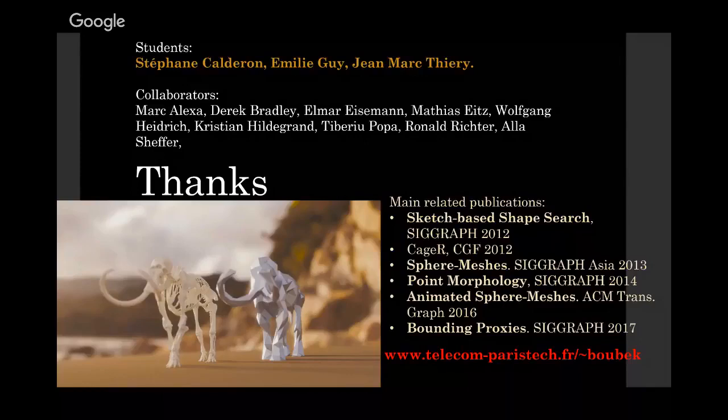Okay, thanks. Martin? I have one question. I've also implemented some mesh simplification algorithms some years ago. I used those algorithms that you showed on your slides, I think from Hoppe from 93 or 97. I've always had the problem that it started to self-intersect, and I didn't find a solution for that. Especially if you have very thin geometry, when you do mesh simplification you start to alter the geometry, and therefore you can get self-intersections. Do you have this problem as well, or did you find a solution?